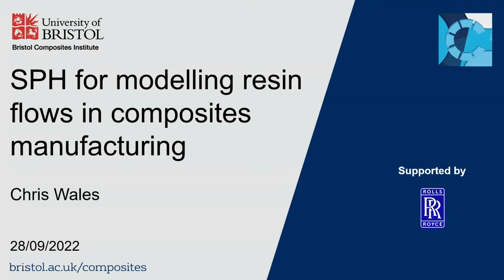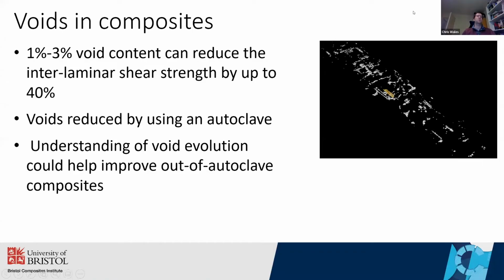So my name's Chris Wales, and today I'll be talking about using SPH for modeling resin flows during the composites manufacturing process. What we're really interested in looking at during the manufacturing process is the formation and the evolution of voids in the composites as the material is cured.